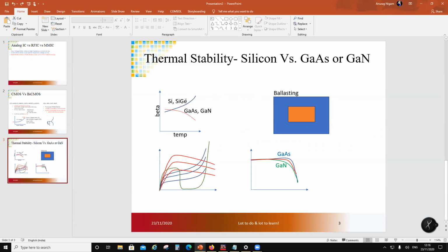In silicon, your hole and electron mobility depends on along what axis you cut the crystal. So basically, your holes may be accelerated in one direction, and your electrons will be accelerated in a perpendicular direction. So you align all the PMOSs along X and all the NMOSs along Y to have the advantage of mobility. So these things are in the layout which you have to be considerate of.